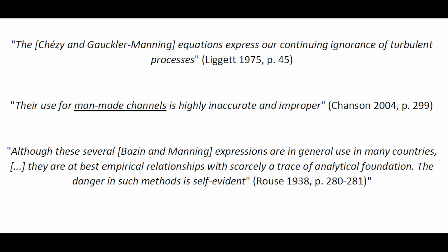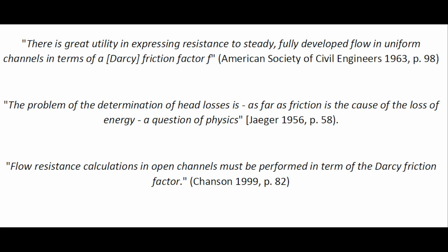A few quotes. The Chézy and Gauckler-Manning equations express our continuing ignorance of turbulent processes. Their use for man-made channels is highly inaccurate. They are best empirical relationships with scarcely a trace of analytical foundation. There is a great utility in expressing resistance to steady, fully developed flow in uniform channels in terms of the Darcy friction factor F. The problem of determination of head loss is a question of physics.